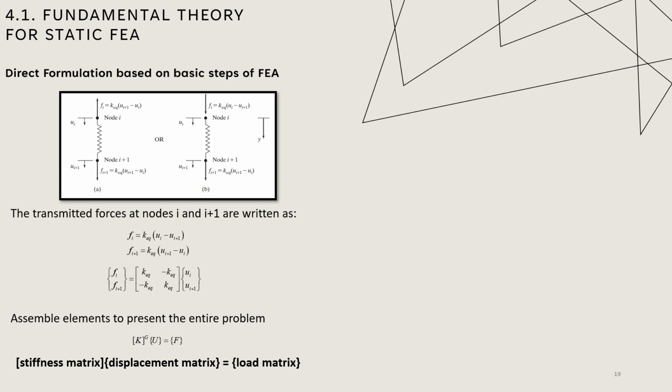And from all of those functions, we connect them together, we get all the elements together, and we get the global stiffness equation Kg. The function below is the stiffness matrix multiplied by the displacement matrix, and you're gonna get the load matrix, and this is the global one.